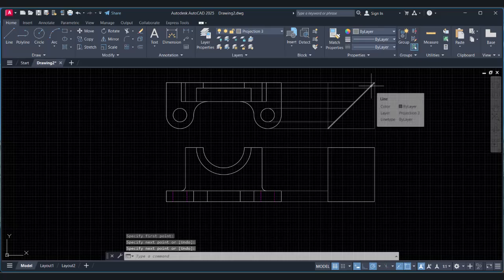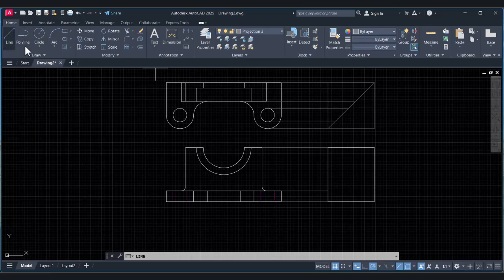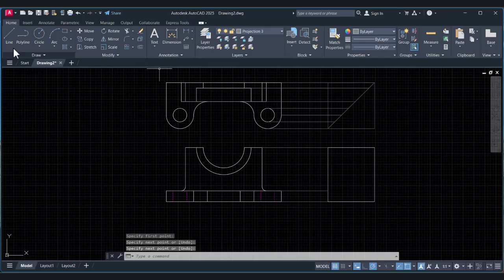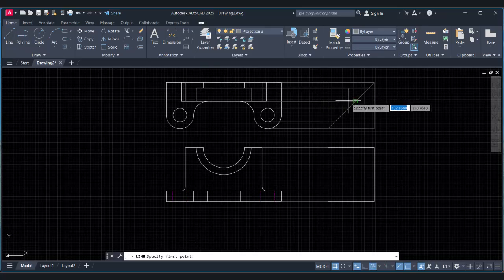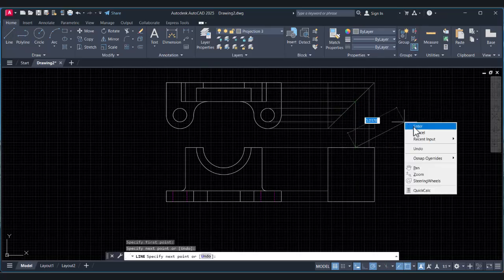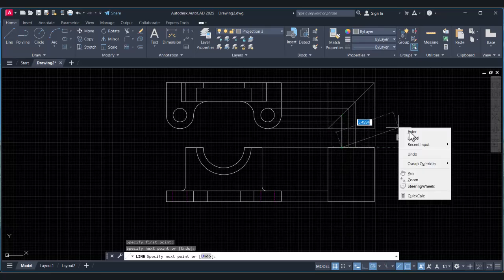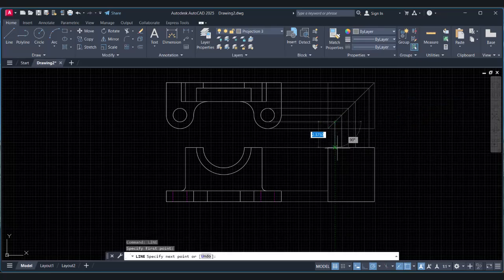If it passes this middle line, we can just trim it. All of these edge points we just draw, and this one is on the same line, so there is no need to draw it, and also we can draw a line like that. Now we are just going to transfer it. From this point to this point, for every point on this middle line, we are drawing a line like that. This way we are transferring the view from the top side to the right side.